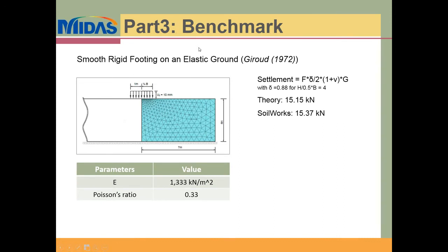So for the analysis, we created a case which was presented by Giroud in his paper. This problem is of a smooth rigid footing which is resting on an elastic ground. You can see the geometry of the problem here. And since the problem is symmetric, we will be modeling only half of the model within the program.